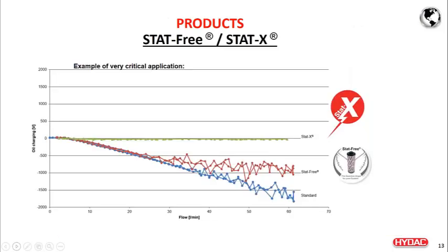So here is an example of the charging behavior of 3 different media. Remember, we talked about the flow, or the hydraulic flux, or the hydraulic load. When you have very high hydraulic load, and the rest is the same operating conditions, same fluid, same temperature, same conductivity, but very high hydraulic flow going through the same surface area of the element, the standard HYDAC Optimicron element tends to get charged more. The stat-free element tends to charge less, and StatX almost charges none.